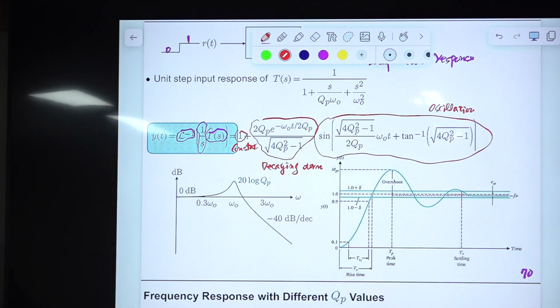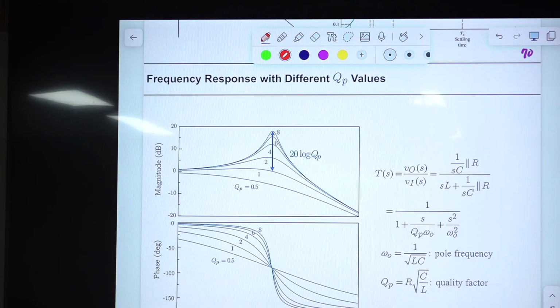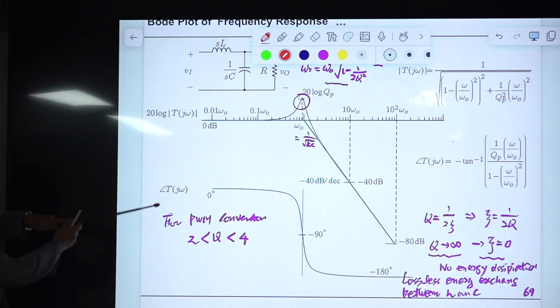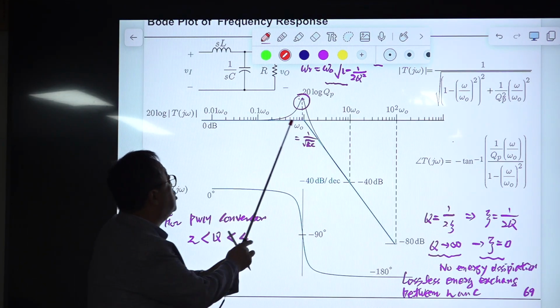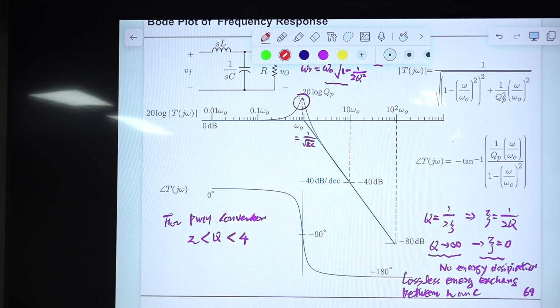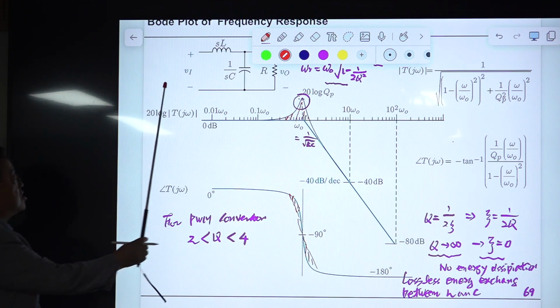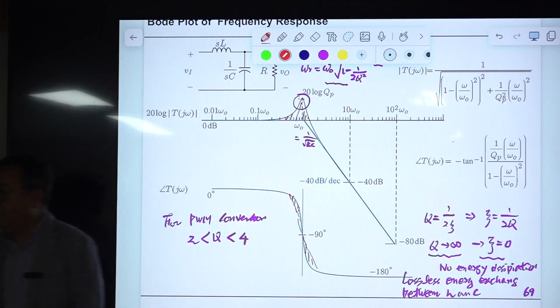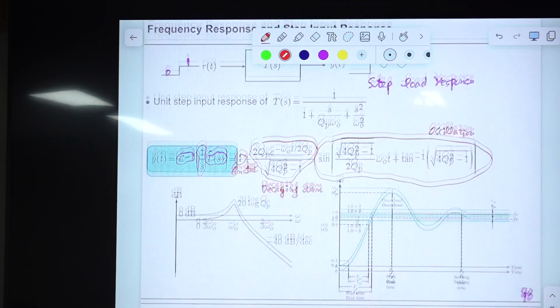Okay, so this is one thing I'd like to mention. And this one, so this is the asymptote, and during this region, it deviates from the asymptote. Okay, this much. So for this particular case, this is the error. So maybe we use straight line approximation, then this might be the error. So behavior of the circuit around this double pole frequency highly depends on the value of QP. So you need some additional information about that.